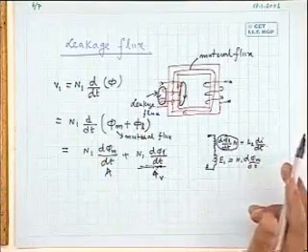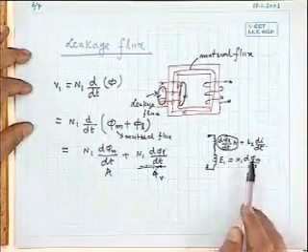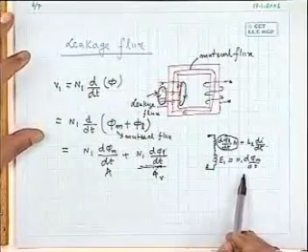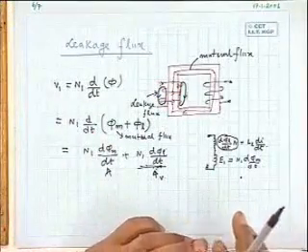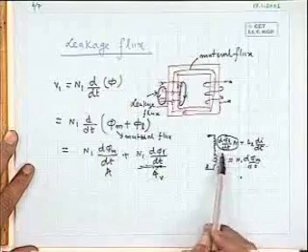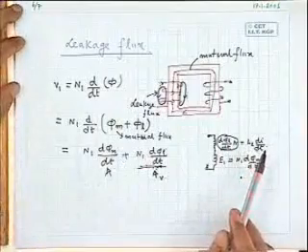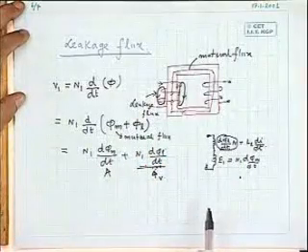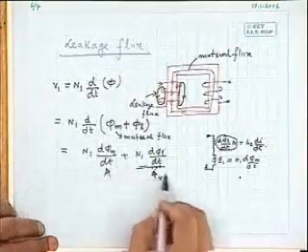As I told you, the voltage induced in a coil is N d phi dt. One can interpret it as L di dt. That is nothing new in it. But why am I not showing this as L di dt? Because this induced voltage I am interested in calculating. So, let us not right now bring any L concept here, because I know how to calculate induced voltage in the primary and secondary, and it is to be supplied to a load. I am interested in voltage. That I have taken care of. But so far as this thing is concerned, this can be taken into account by a leakage reactance connected in series with the coil.